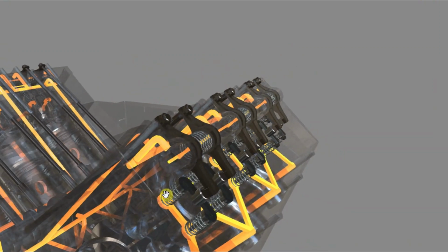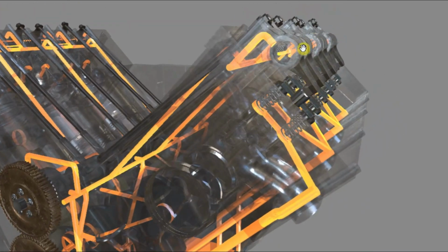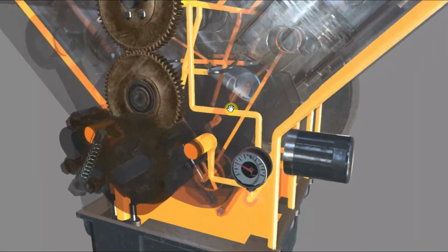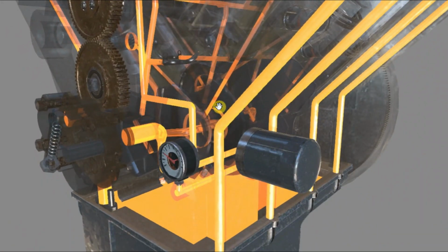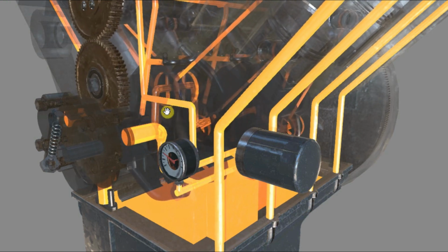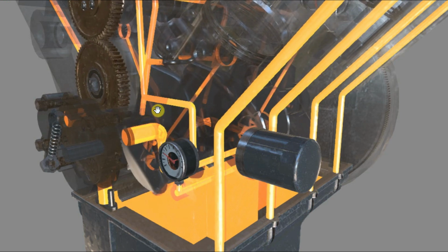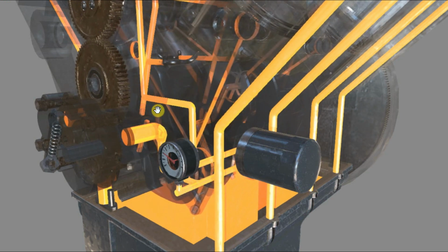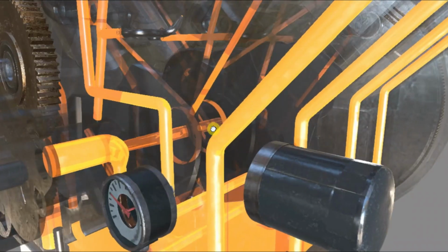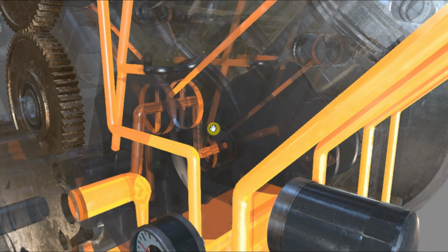What you have to understand though is that the rocker arms are the least of our worries. These are relatively lightly loaded and they're not going to generate a huge amount of friction. However, when we get down and we start looking at the pistons, the crankshaft, the camshaft, you can see the crankshaft rotating right now. They all need to be lubricated, because if not, the engine will overheat very, very quickly.